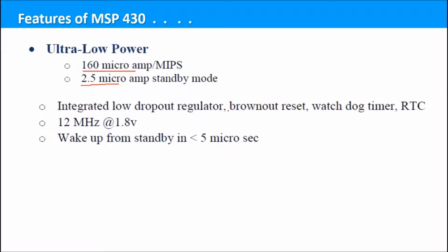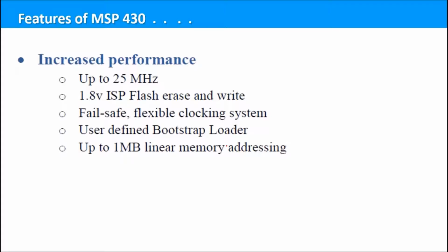Integrated low dropout regulator, brownout reset is available, watchdog timer is available, and RTC, that is real time clock, is also available. In the coming lectures, I'll discuss all these circuits in detail. Then it operates on 12 megahertz frequency with a power supply of 1.8 volt. From the standby mode, it will wake up in less than 5 microseconds.